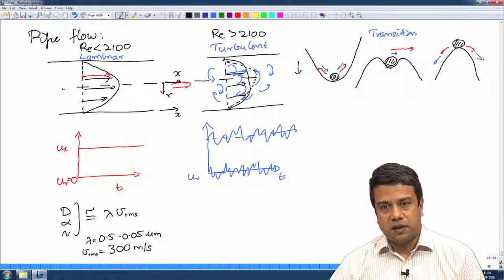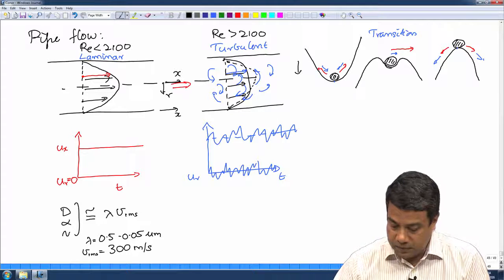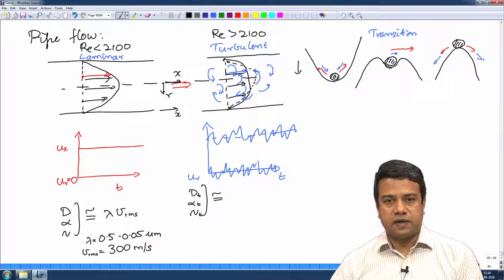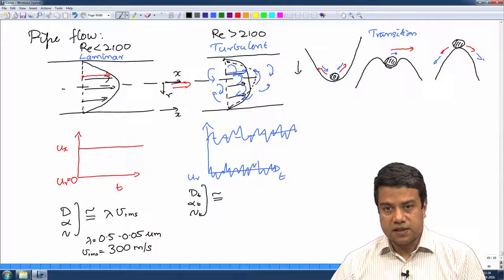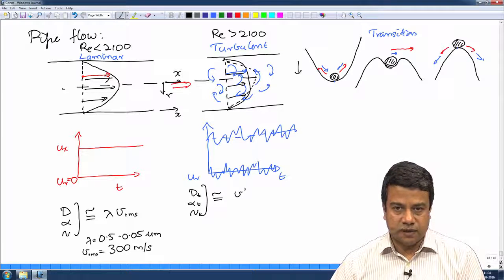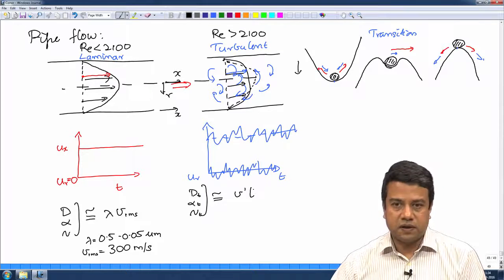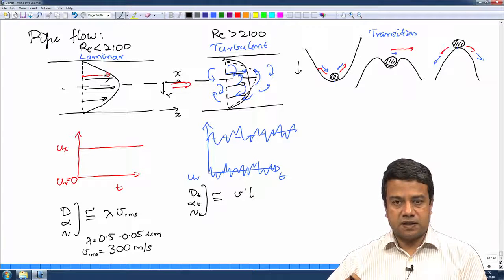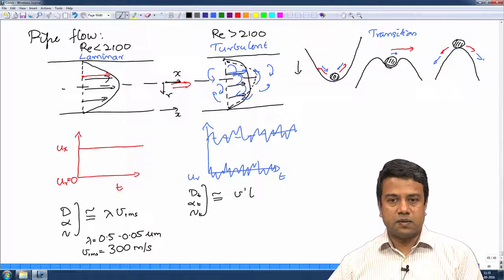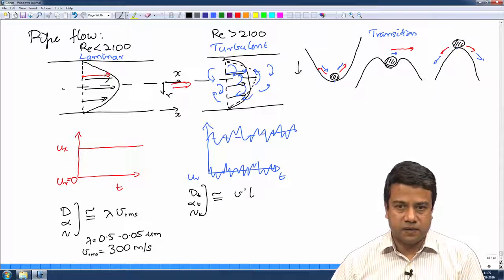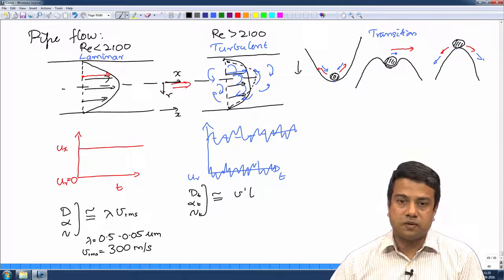In a turbulent flow, at the simplest level, one could also define turbulent diffusivities. These will scale as the velocity of the turbulent fluctuations times a length scale for the turbulence. And that length scale for the turbulence is what is called the eddy size, the eddy length scale. So, you have a length scale for the eddies, a distance over which there is correlated motion. This correlated motion is what is transferring mass, momentum or energy. Therefore, you have a length scale for the turbulent eddies and you have a velocity for these turbulent eddies. And at a simplistic level, this product is what would give you the turbulent diffusivity.